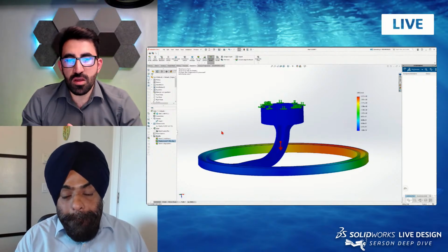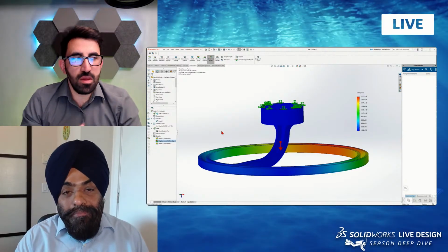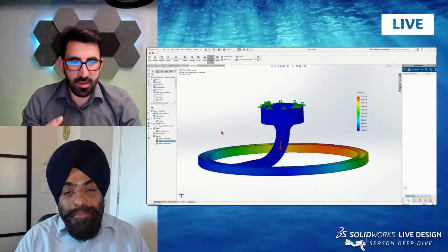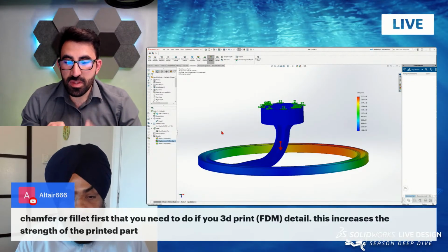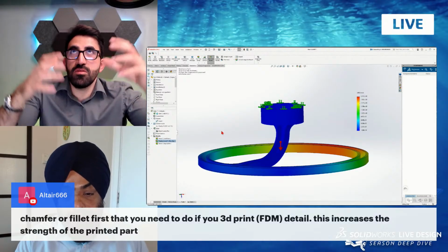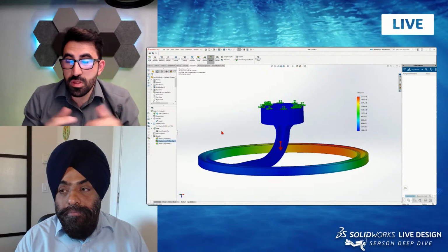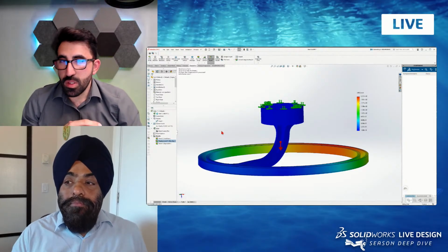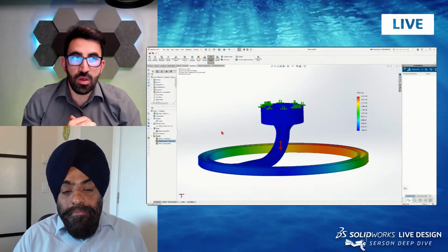Otherwise, I could just create this from stainless steel, and I'm sure it's not going to bend, but it's going to be a very heavy component. It adds to the FMEA table, the risk, because during the installation, if it falls on your feet, it might even do serious damage. So there are different parameters you need to take into account before